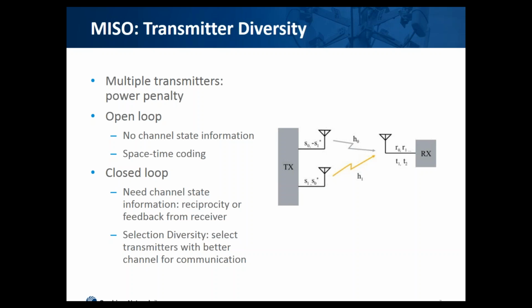There is also a complex conjugate component here, which we can ignore for the moment, which is also used to make the math easier at the receiver. The important concept here is that we repeat the same two waveforms, but swapping the antenna they are transmitted from. Why do we do this? Well, if the channel between the first antenna and the receiver is temporarily better, then each of the two signals has a chance to be sent through that. Remember that in this case, we don't have channel state information, so we don't know which one is better. The only option is then to try both.